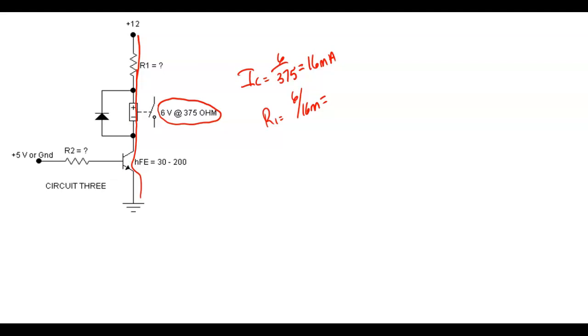That's the part that kind of got me confused too. The 12 is plus 12 at the very top, R1. We just calculate the 6 volts, due to the fact that it's reverse biased, and that's the reason for 6 volts over that 16. Right now you need to just ignore the diode. So it's just reverse bias. Gotcha. So you're right, it should have been 6 volts, Janice, I'm sorry. But it's not going to change the size of the resistor. So I need to make that correction. I don't know where I came up with 5.9.